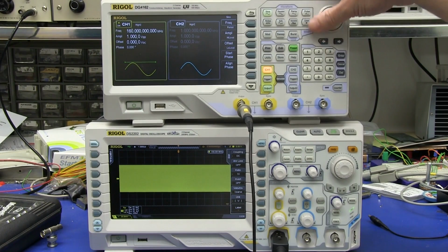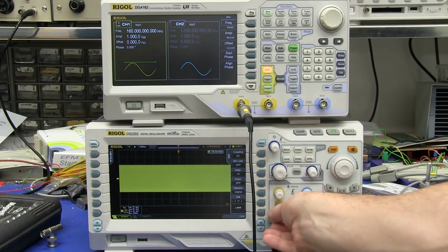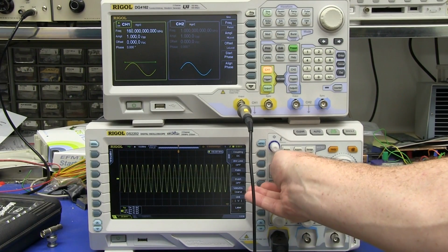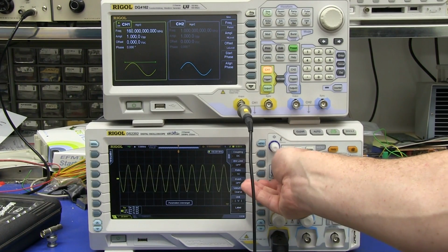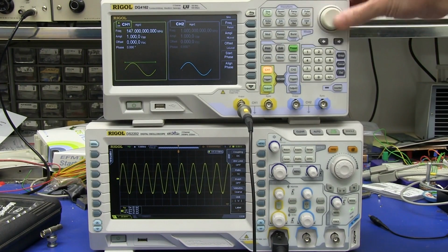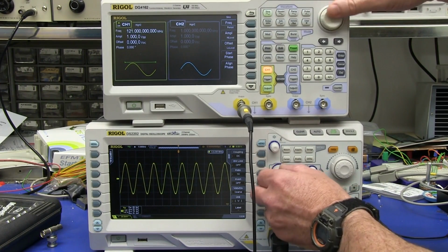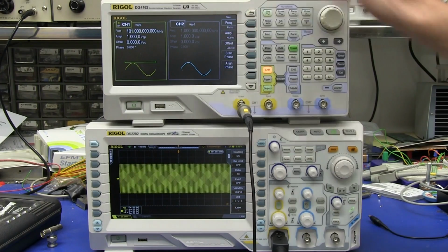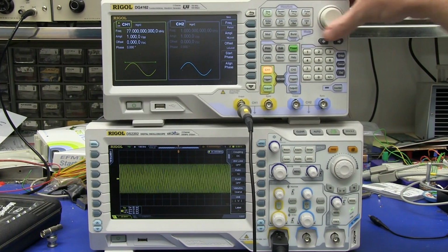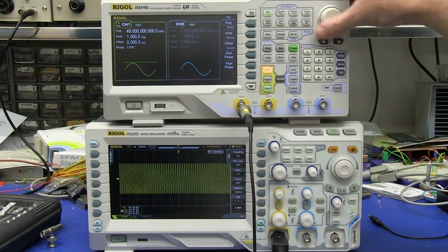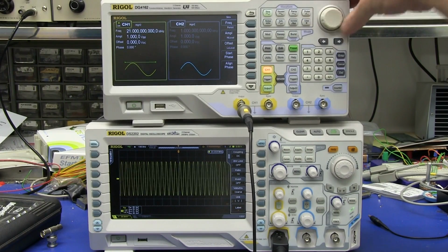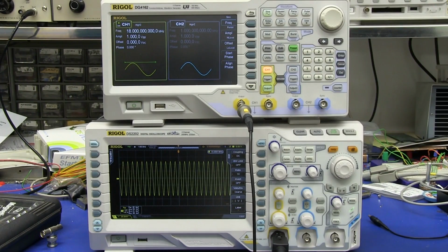So that's probably the amplitude stability of this Rigol function gen. But we're up at 160 megahertz now. And 160 megahertz is the maximum frequency of this sig gen. But there you go. It basically did not drop in amplitude. There's a little bit of change there, but the amplitude stability of this, I don't know the spec. But basically, that probe is just fine. It is not attenuating at all because it has a rated bandwidth of 350 megahertz on ×10 mode.